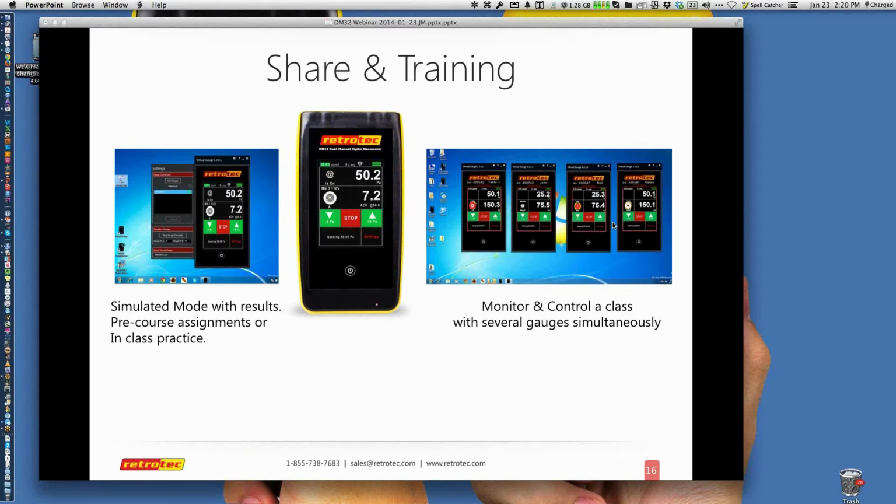Then I can actually have 2 gauges running. So if you look at the image on the right, instead of having 4 gauges, maybe I only have 2 gauges, and they can be running together on my PC, and I can now control my blower door and my duct tester at one time on my PC. It's in my kitchen, so it's a lot easier to not have to run back and forth, asking am I still at 50, or dealing with all these hoses and tubing and wires to try and figure out a way to see both gauges together. It's now just as easy to do one location on your PC, and now I can control multiple fans and gauges from one location.